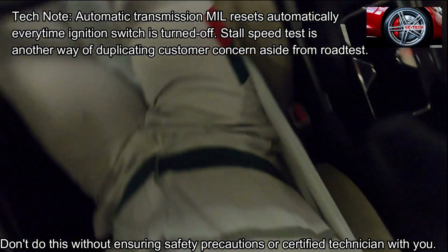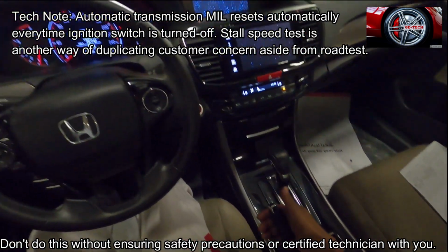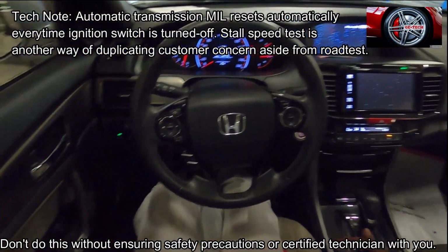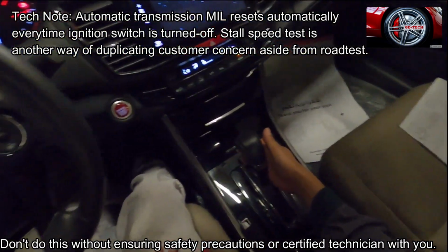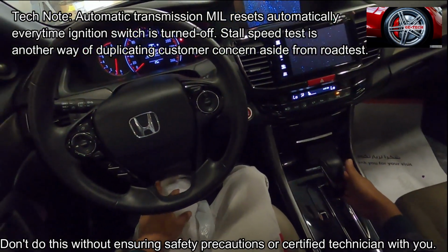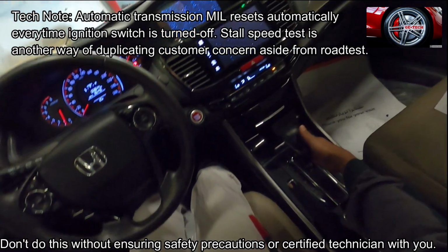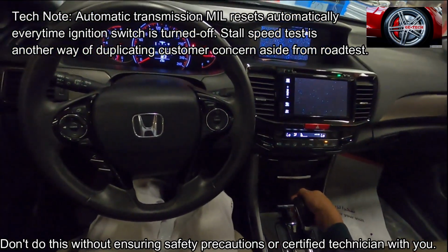Okay, the first thing we have to do is apply the parking brake, and then since this is automatic transmission, the left foot should be on the brake pedal and the right foot is for the accelerator pedal.